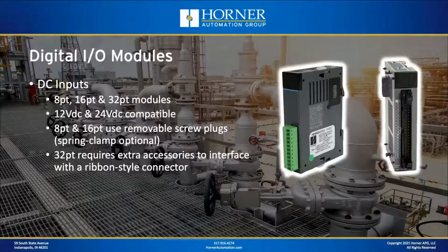However, that uses a high-density ribbon-style IDC connector, which means that it's going to take extra accessories to interface to it. Now, we sell those accessories at Horner, as do companies like Phoenix Contact, Weidmuller, etc. Those companies probably have a wider variety of those accessories than we do at Horner. So again, if you're going to use the 32-point input module, you need extra accessories.